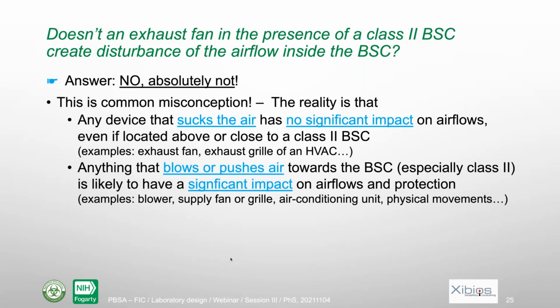The next question is, does an exhaust fan in the presence of a class 2 biosafety cabinet create disturbance of the airflow inside of the BSC? I termed that as a question, but actually it was a kind of assertion from one of you. Clearly, the answer is absolutely not. This is a common misconception, and even some engineers don't see that very clearly. But the real thing is that if any device sucks the air, it has no impact on airflows and no impact on the functioning of a class 2 biosafety cabinet.